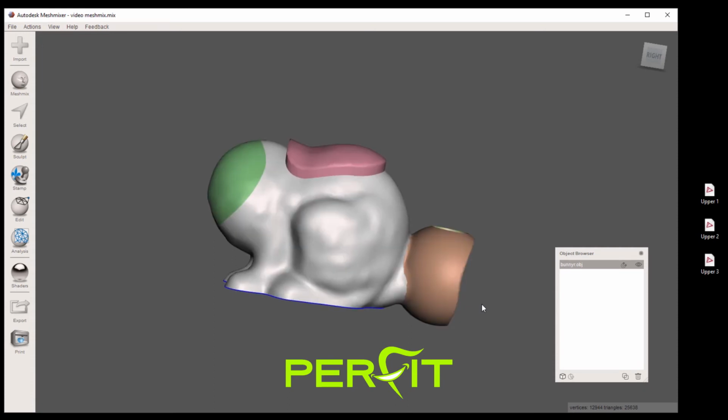Let's recap on what we learned during this video. We know where to go to download Meshmixer and how to install it. We learned how to move, rotate, and scale our object by using the manipulator. We covered the very basic sculpting functions, and we brought our attention to look at the wireframe mesh triangles of our object. We know how to do simple Boolean union and Boolean difference functions. We also learned how to use some of the very basic select tool functions without going into too much detail. All of these tips will come in handy when working within Meshmixer.